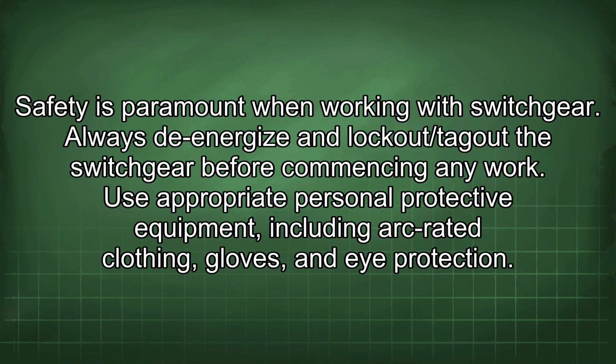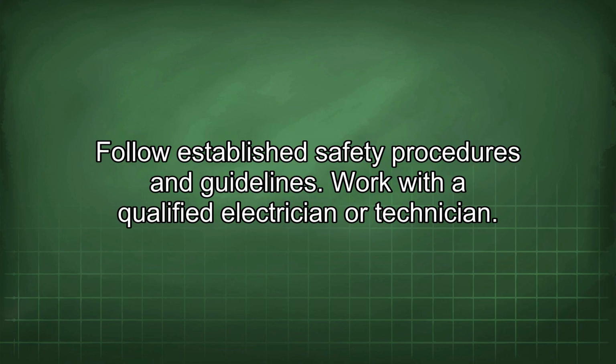Safety is paramount when working with switchgear. Always de-energize and lockout/tag out the switchgear before commencing any work. Use appropriate personal protective equipment, including arc-rated clothing, gloves, and eye protection. Follow established safety procedures and guidelines. Work with a qualified electrician or technician.